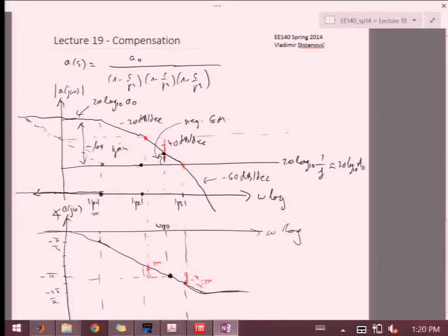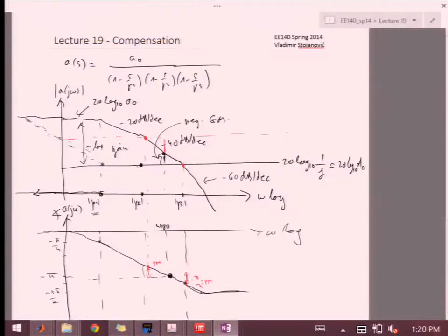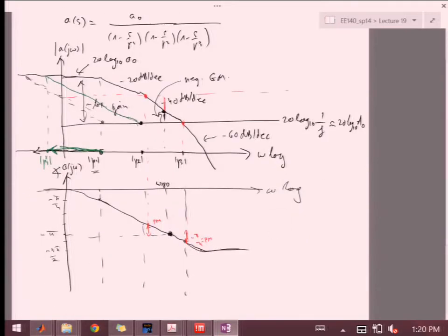So we're going to have a situation here that we go in parallel. This has to be 20 dB per decade slope because it's only originating from this new location of the pole. This is going to be P1 prime. So our pole 1 has shifted all the way here. Okay. And if that happens, then you start breaking the phase right over here.